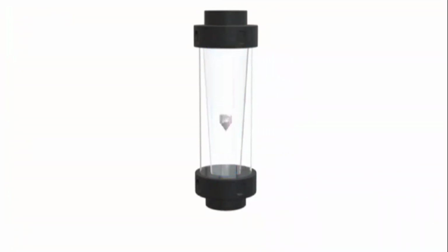A rotameter is a flow meter used to measure the flow rate of fluids, typically liquids or gases. It consists of a tapered tube and a float which moves up and down as we adjust the flow rate of the fluid using the knobs provided in the rotameter. The position of the float is proportional to the flow rate of the fluid, which can be measured by the scale on the outside of the tube.